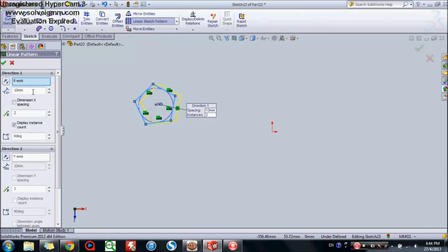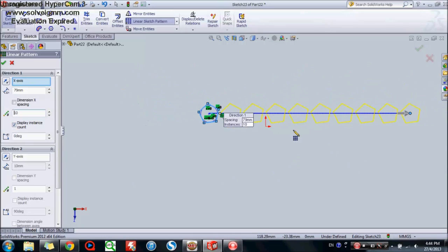So for the options, I want distance to be like 60 mm. So as you can see the distance here. So I want to set it like 79, until they are not intersecting with others. So you can choose how many you want to copy. Okay, so I'll copy like 10. So I just click enter. You get 10 similar things aligned with each other.